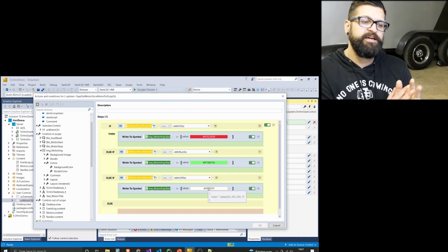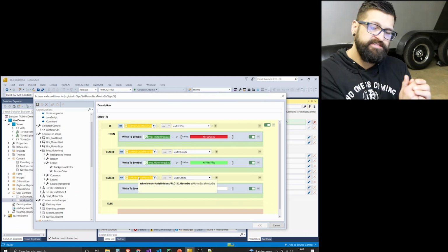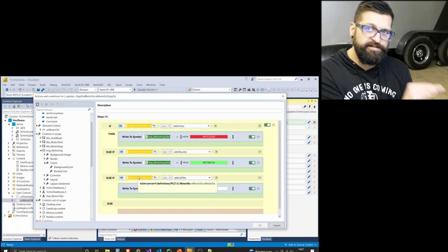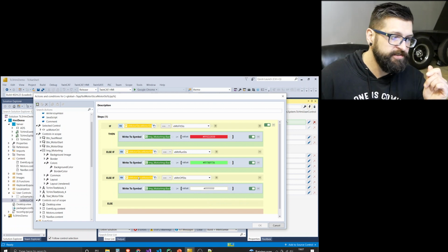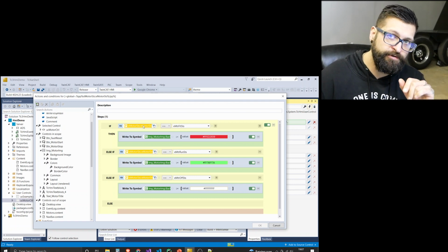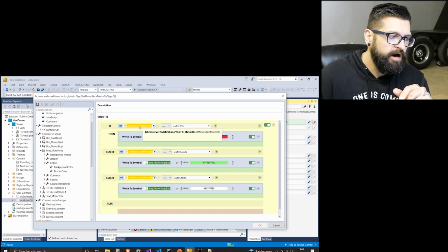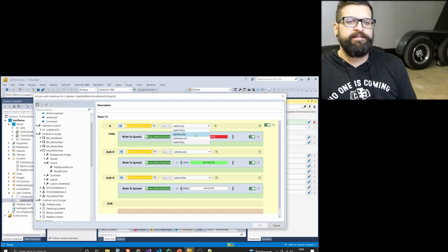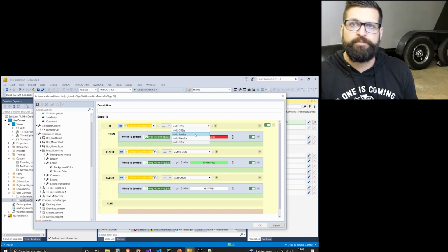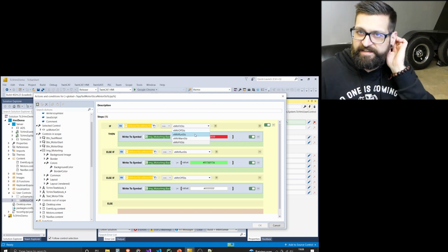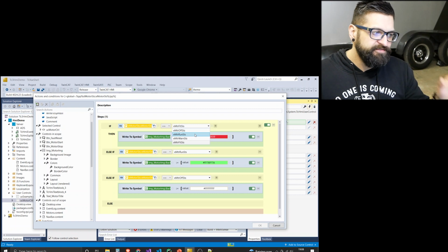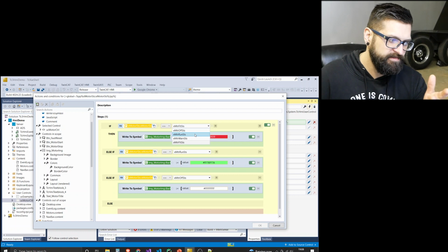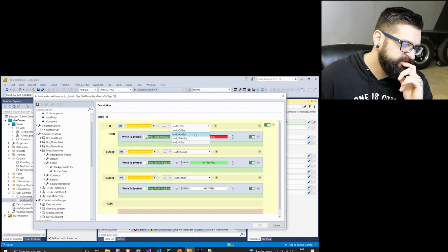Remind you, this isn't a directly bound symbol in the PLC. This is a parameter in the HMI that we're going to pass PLC symbols into. And also, it's really nice to know that because when I mapped this motor structure that contains that enumeration, my drop downs over here automatically correspond to what that type is. So you don't have to worry about, well, what was my integer 1 for my enum? What state does that represent? It's a really nice thing to do, to map your symbols over, because then those data types are reflected in the HMI project. So I know exactly, well, I want fault status. I can click fault status. It's a very cool feature.